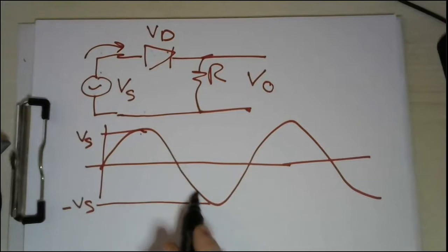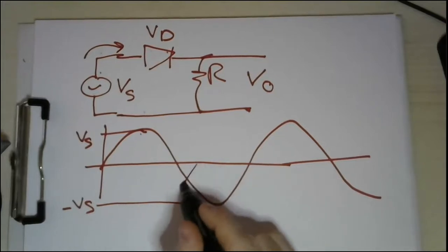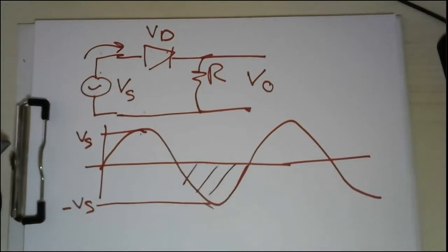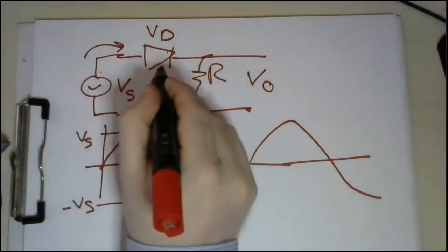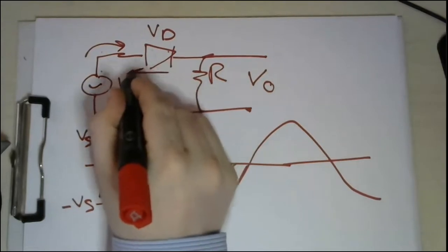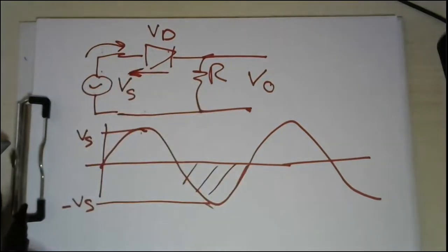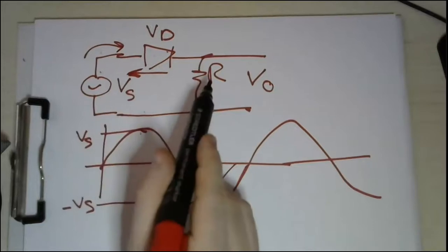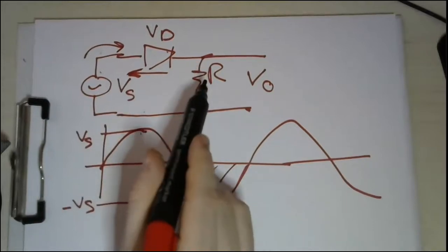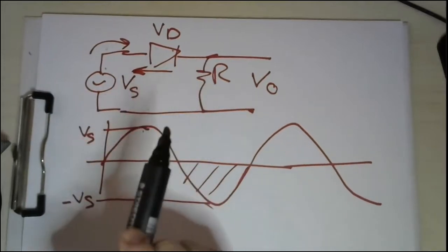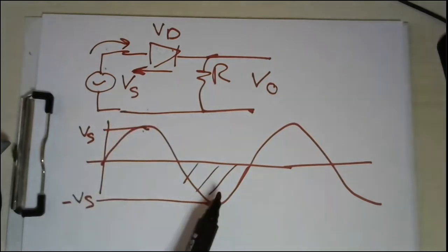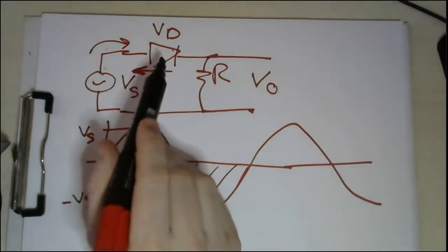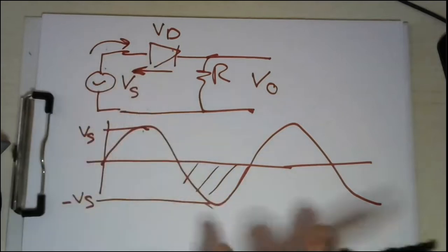However, whenever you have a negative voltage, which is the negative half cycle of the circuit, this polarity will reverse, and then current should flow in this direction. Because now this voltage is negative, and this is grounded, so it will flow in this direction. So in this case, your diode will be treated as an open circuit. Accordingly, you can say that